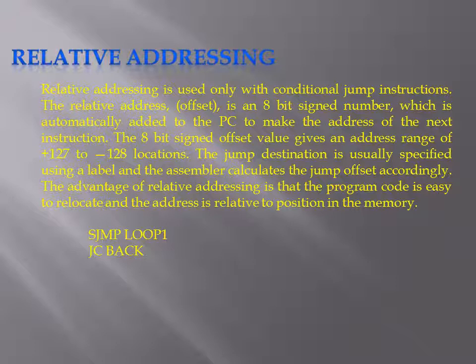Relative addressing is used only with the conditional jump instructions. The relative address, or offset, as we call it, is an 8-bit signed number which is added to the program counter.